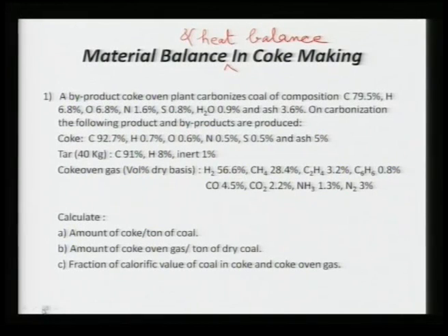Now, you should also note this problem as information about the various compositions that enter typically in the coke making process. Coal composition you should note, and coke composition you should also note. You should also see the analysis of coke. It contains typically sulfur also, and when this coke is used in the blast furnace, the sulfur from coke is one of the sources of sulfur in pig iron. So, one has to control the sulfur also. However, this sulfur you can only control by controlling the amount of sulfur in the coal. So, that is what you should see in the analysis which is given here.